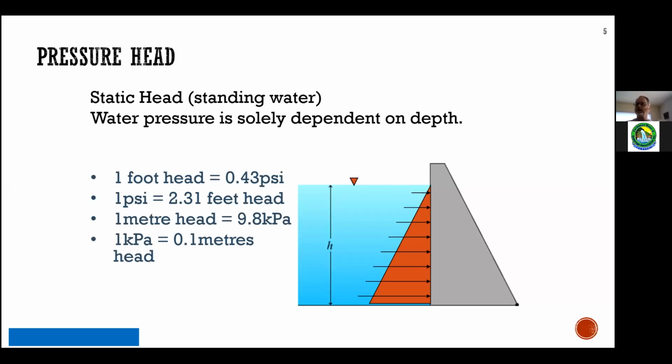And if you look around and you see higher buildings or changes in topography that change elevation, the energy has to be higher than that highest elevation. Otherwise, those delivery points get no water. There is no way to deliver water at a higher elevation than what your system is delivering. And that's really what we're doing when we design our water system.